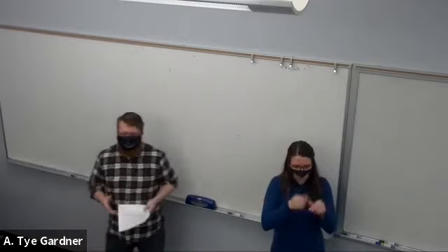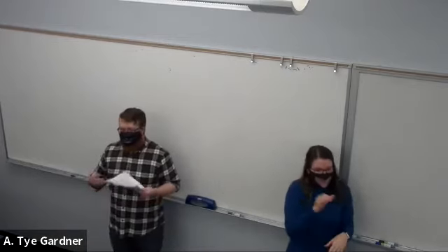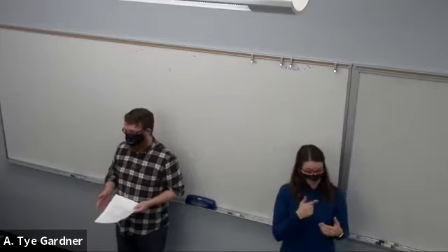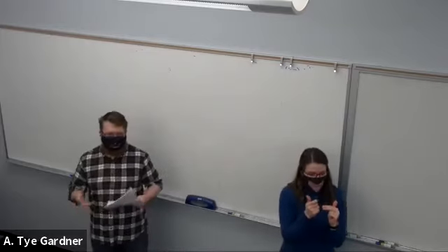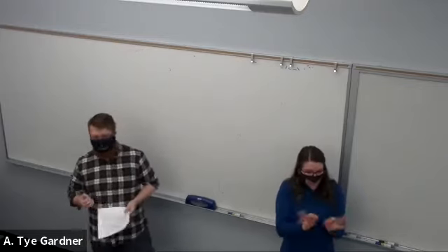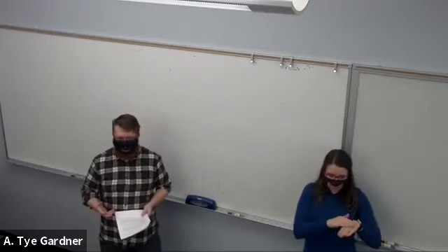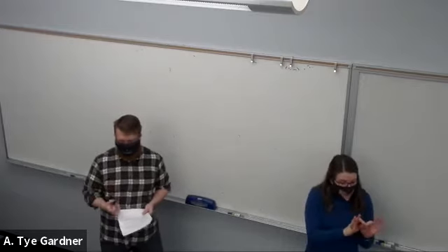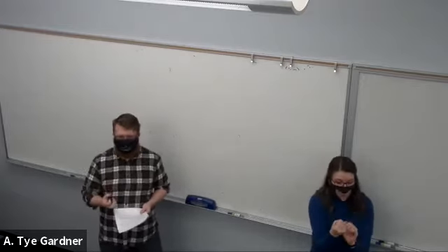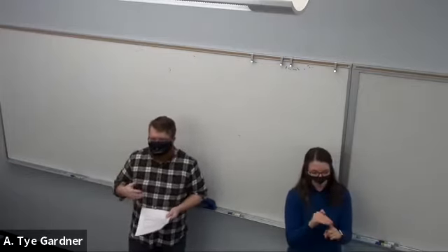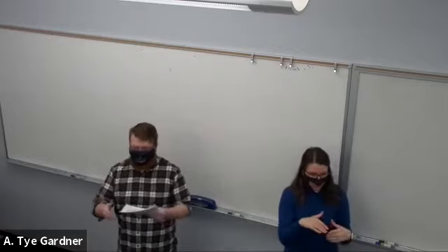So what we're going to talk about today is really the foundational building blocks of how do we get memory out of circuits? How do we build something that remembers a value? Now, the basic building block of this is going to be what we call a latch. And all that means is it takes a value and it latches onto it. It holds onto it and won't change until you nudge it off of it, right? It's until you give it a new value.